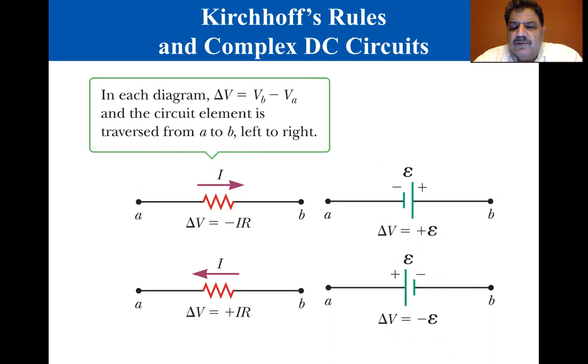When applying Kirchhoff's rules, you must make two decisions at the beginning of the problem. Assign symbols and directions to the currents in all branches of the circuit. Don't worry about guessing the direction of a current incorrectly. The resulting answer will be negative, but its magnitude will be correct, because the equations are linear.